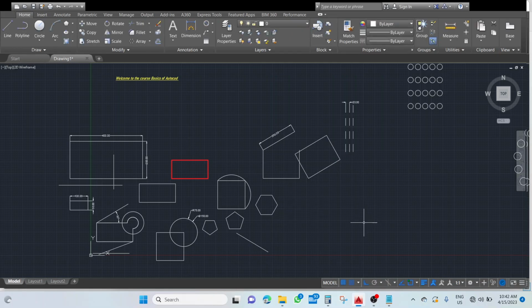So just close this one. Now here you will see center and hidden. Initially the center and hidden line was not there. This option was not there, so I have loaded this option. Where I have loaded: go into the other, go into the load, then click over here, just type C. So center is coming over here, just click OK. Okay, already it is there. Just press OK. After pressing OK, these lines are visible.